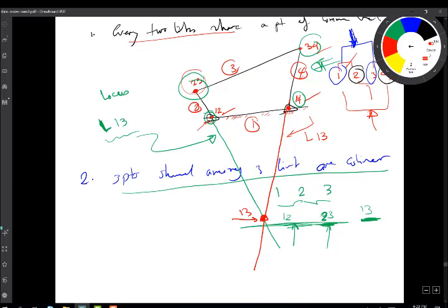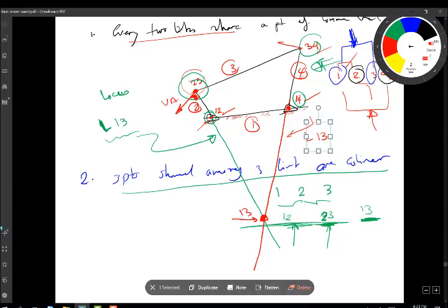Now, remember in the last lecture, we also found point 1,3 by drawing perpendiculars. At this end we call the point A, and draw a perpendicular to the velocity VA. Then we did the same with the velocity at the other end, VB, and extended the two perpendiculars until they intersected.